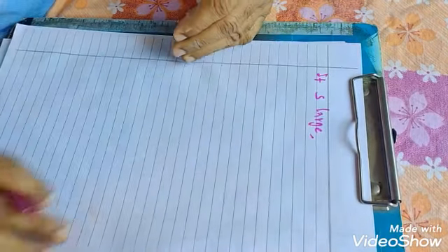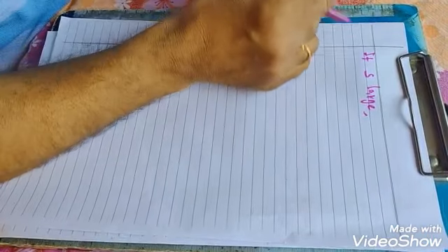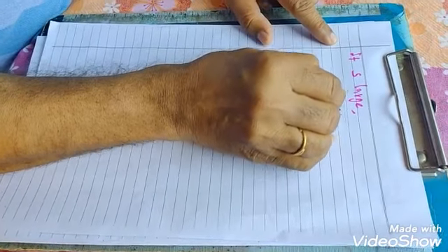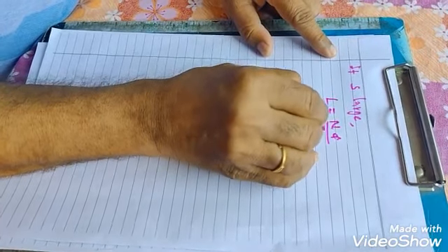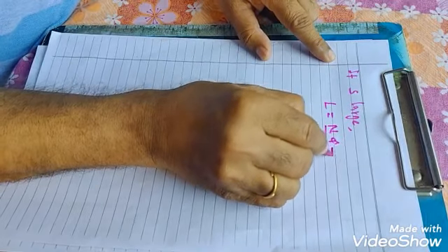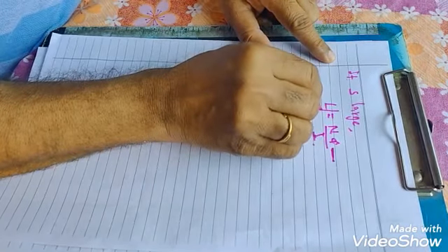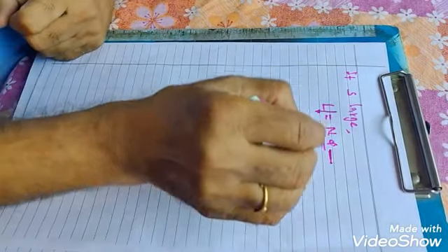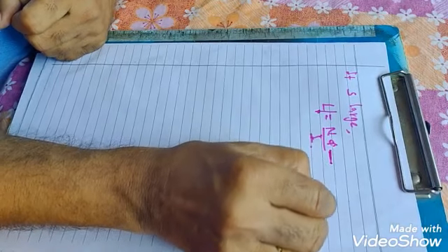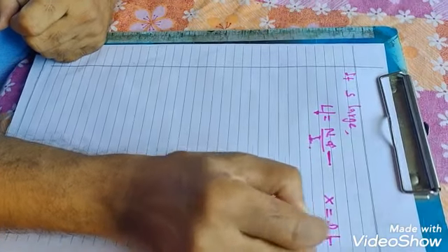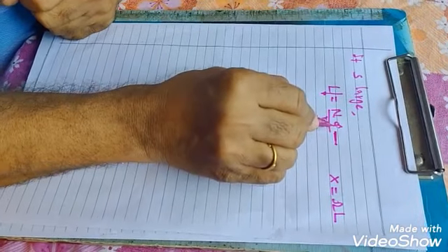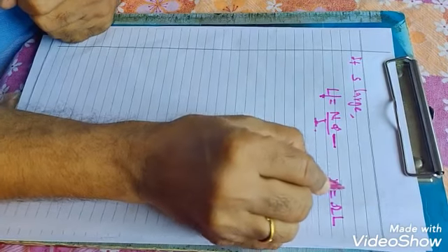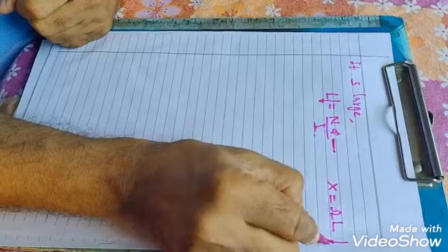And therefore leakage reactance decreases, because leakage reactance depends on leakage flux. Flux is decreasing, so leakage inductance is decreasing. Leakage reactance X is omega L. So as leakage flux decreases, leakage inductance decreases, therefore leakage reactance decreases.